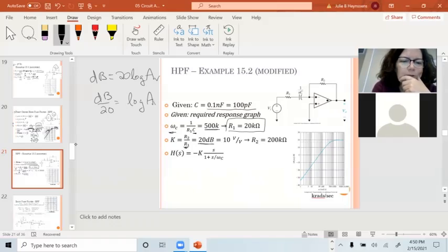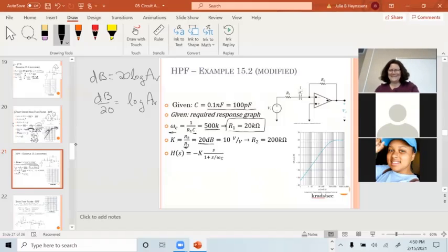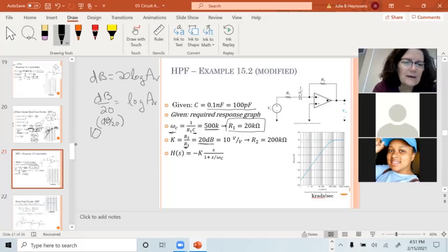And this is where you start sweating because you don't remember Algebra 2 from high school and you haven't used logarithms since then. Well, don't you just raise 10 to the power of dB over 20? Yes. I'm getting there. Some of you remember that better than others. There's probably about half the class that doesn't remember that one. The inverse function of log is 10 to the power. So if I take 10 to the dB over 20, 10 to the log of something cancels each other out. It's an inverse function, and that just becomes AV.